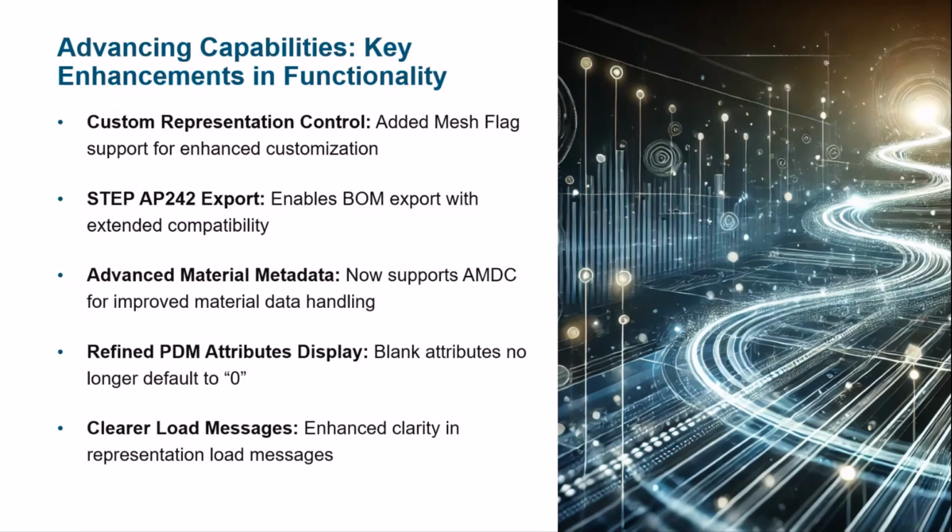The next big change you will see is representation load messages. We have replaced the single message with multiple ones with enhanced clarity in representation load messages. You can actually create the part sets on the parts that have failed representation creation using the batch mesh workflow, and the message is very clear, telling you what has worked versus what has not.